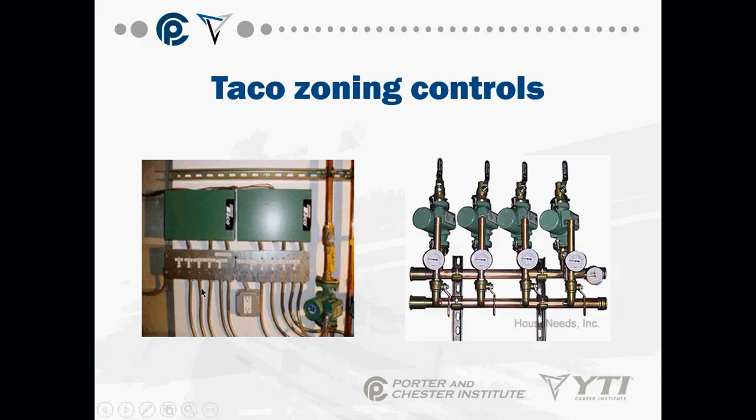Each one of these is actually getting piped to one of these circulators. Basically kind of looking like this, as you see here. So circulators are able to move the water at a further distance versus what a single circulator and zone valve configuration would do.